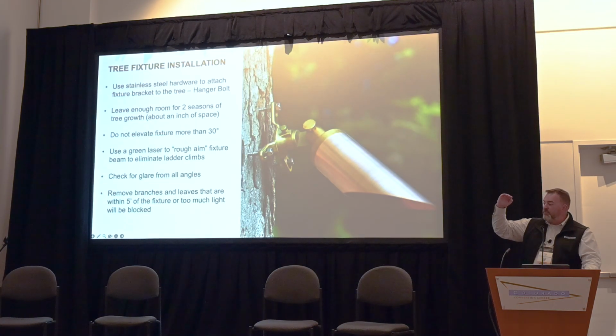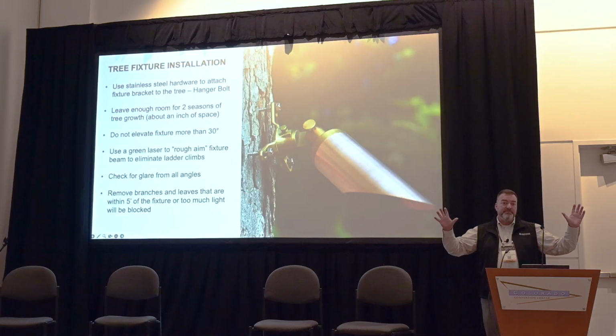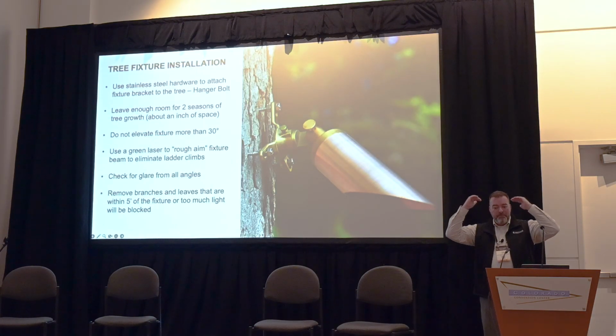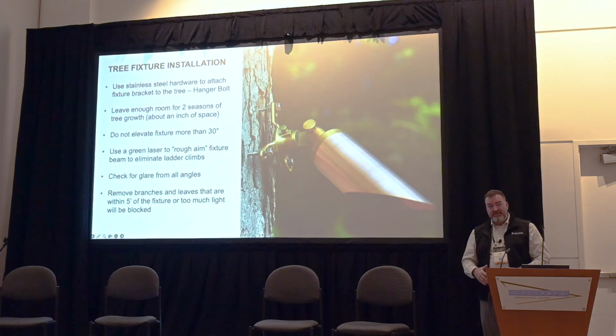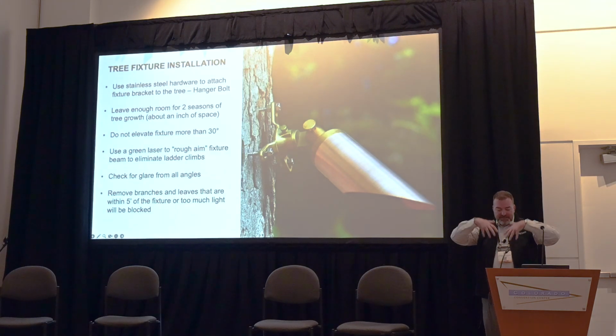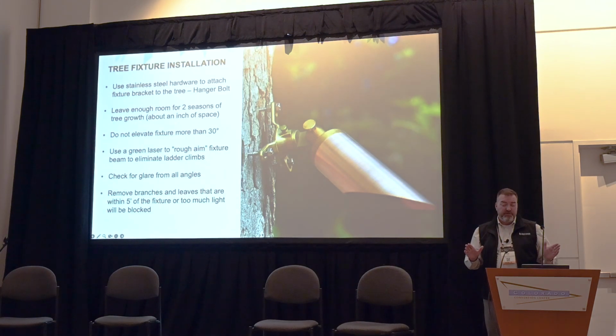And then underneath, when you're doing tree downlights, it's an awesome effect. Anytime you can use the trees above you instead of path lights, it's always better, because anytime you can mount from above and minimize hardware on the ground, it's always better. You don't have to worry about frost heaving, knocking it over, or getting it kicked and destroyed. It's always better.